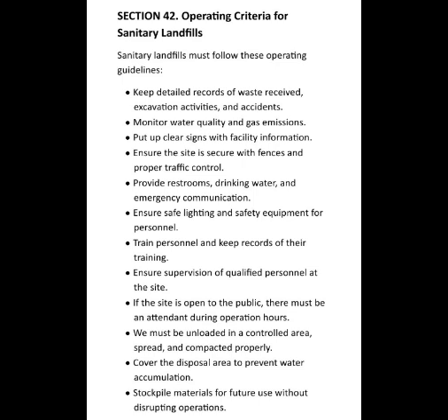Ensure safe lighting and safety equipment for personnel. Train personnel and keep records of their training. Ensure supervision of qualified personnel at the site. If the site is open to the public, there must be an attendant during operation hours. Waste must be unloaded in a controlled area, spread and compacted properly. Cover the disposal area to prevent water accumulation, and stockpile materials for future use without disrupting operations.